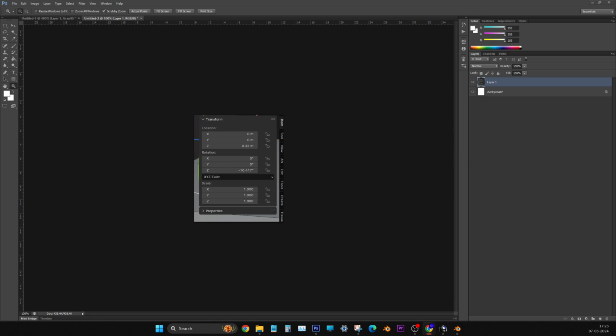Now, before that we have to do one more thing. If you see, no, the staircase will be flat actually. It won't be on the bottom, you won't be able to see this, right? So we have to do one more shape modification. Go to edit mode. Press F, press dot on the keyboard, numerical.